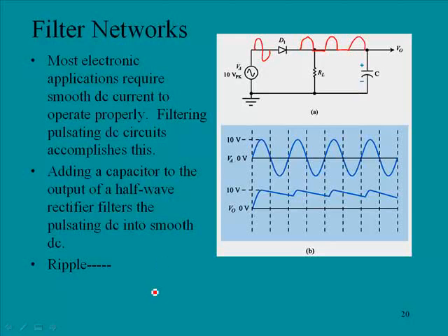Now in this case, I'm going to draw a little bit bigger picture of it down here. What is going to happen is that peak value is going to come in right here, and it's going to charge this capacitor, and it'll charge to the peak value, and then the capacitor will begin to discharge, and it will begin to discharge until again another peak value comes in and recharges it. And so it recharges to the peak, and then it begins to discharge, and then another peak comes in, charges it, and so you end up with an output that looks kind of like this drawn right here.